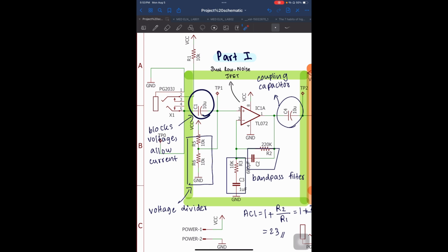In an audio amplifier system, a microphone acts as a transducer by converting sound waves into an electrical signal. A preamplifier boosts this electrical signal from the transducer to a line level so it can be further amplified to drive the loudspeaker, producing the final output sound. It amplifies typically a voltage gain between 10 mV to 1 V, but does not provide current. The op-amp amplifies the audio signal, adding or reducing subtle shades in the sound character.